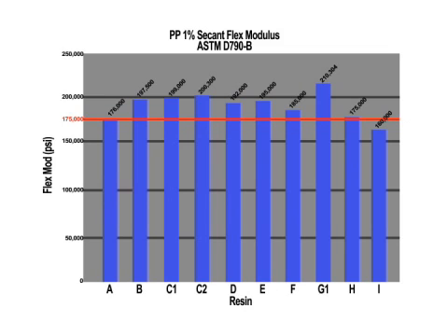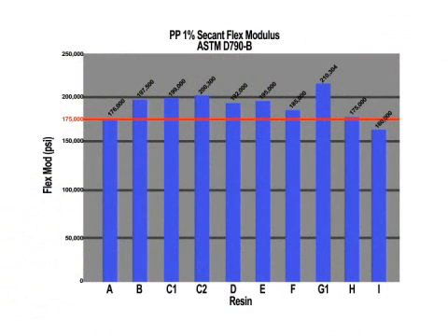When we show performance limits such as hydrostatic limits, minimum and maximum fill height in our drainage handbook, our detailed drawings, any of the information that we provide to you as a customer, we are doing so with the minimum values that we have stated in our product literature as well as in this presentation. We verify that through a quality control procedure that makes sure that the product that we are producing and providing to the field meets or exceeds those lower limits.